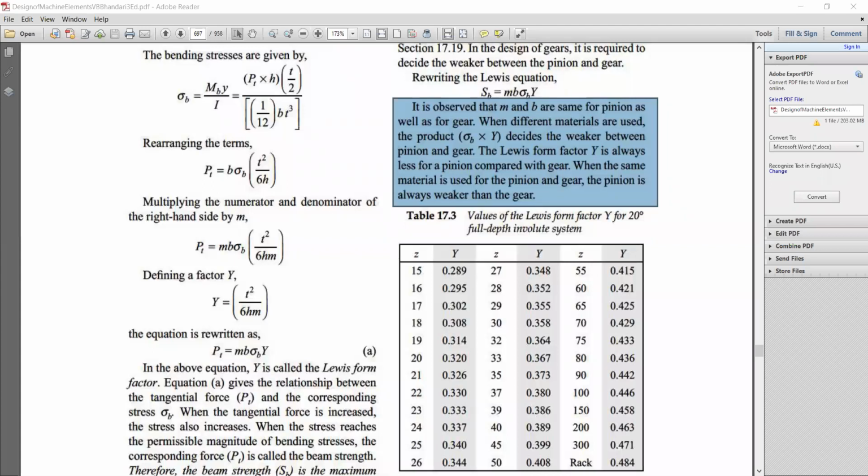Now this is a proportional diagram of a spur gear, or you can say spur and helical, both are the same, only the helix angle will be there. So refer to the spur gear. After the completion of the design you need to draw a schematic diagram like this, and you have to list out a few standard dimensions which are given by empirical relations. So based on the empirical relations you should find out the different dimensions.